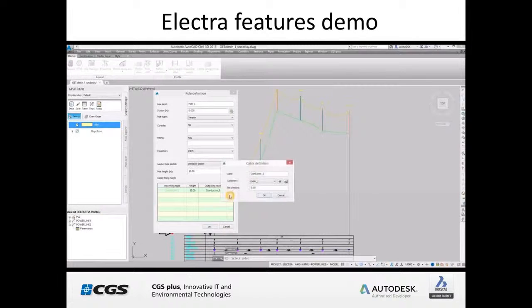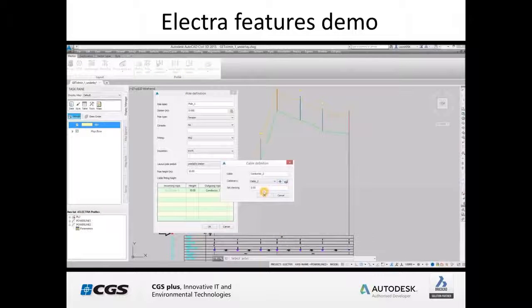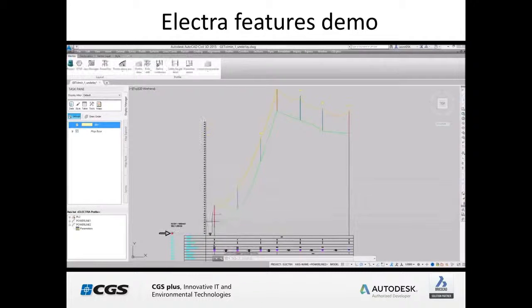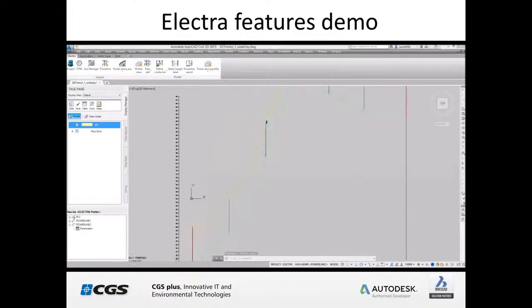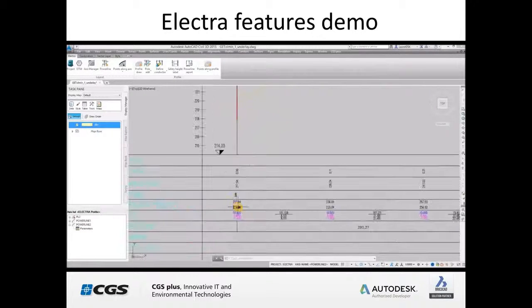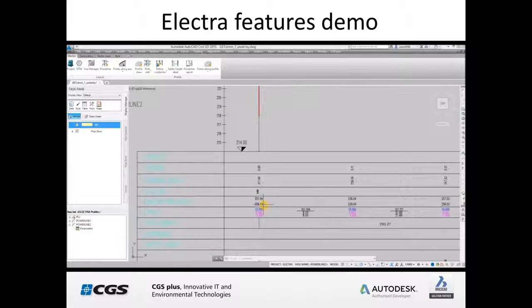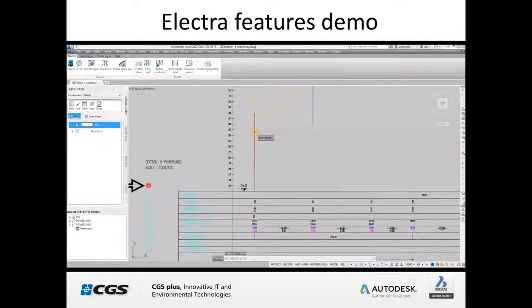Here we'll show the possibility to add more conductors to that power line span. So we always select the first tension pole on which we attach cables. We define some technical parameters for the cables, and then we have to define the attaching point, so basically the height at which the cable will be attached to the pole. So here we have now 2 cables added to this span section. And in the bottom you can see that the conductors' height and the poles' attaching point heights are represented, and bear in mind those values below.